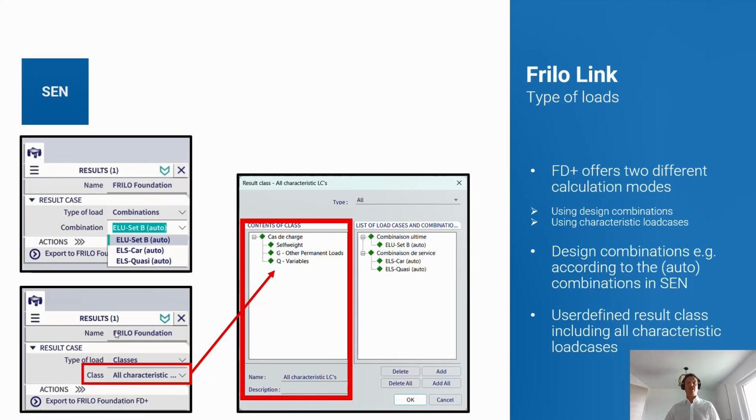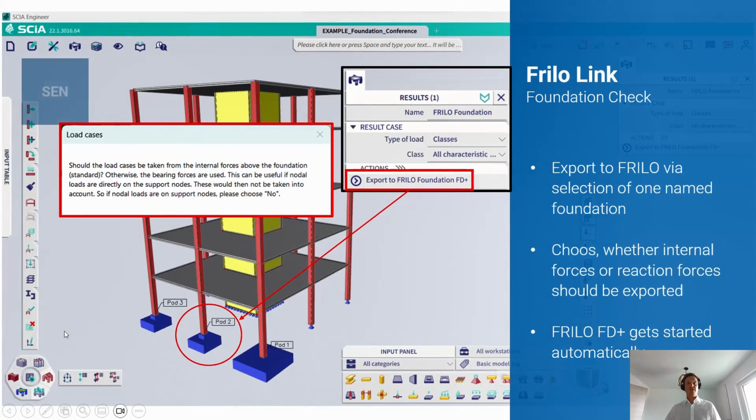That's why my suggestion would be, if nonlinear calculations and additional internal forces according to theory of second order have a minor input on it, just hand over the characteristic load cases and make the foundation module build the proper combinations itself, because it knows how to build them and how to steer the different checks that need to be handled.